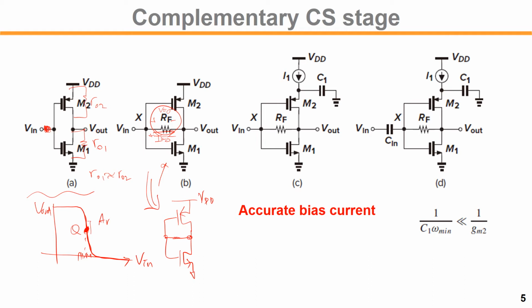In that case, with this electrical equivalent model, we have VTH plus overdrive 1, VTH plus overdrive 2, properly generated for the different sizes of P and N. For any size, you will find the right overdrive voltage, so that this ensures M1 and M2 are in saturation, right?